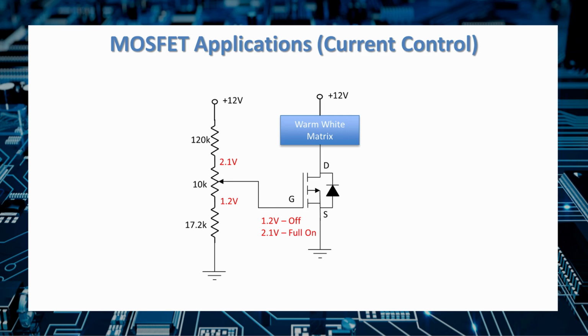I didn't use that voltage divider in the lab example that I'm going to show you, and you'll see that I have a very hard time with precise current control. Without the voltage divider, only a very small portion of the 10K potentiometer's range is giving me the control. It doesn't take much of a turn to get past the threshold and put the MOSFET into full conduction. Here, let's take a look.